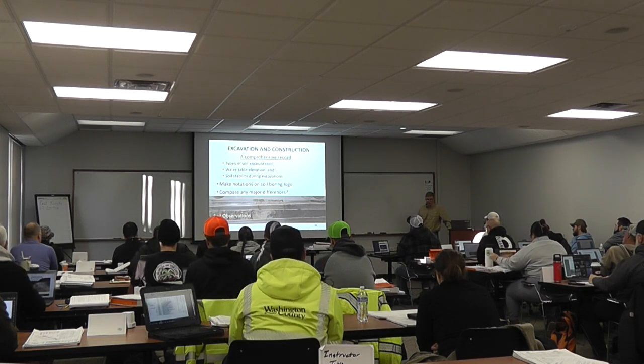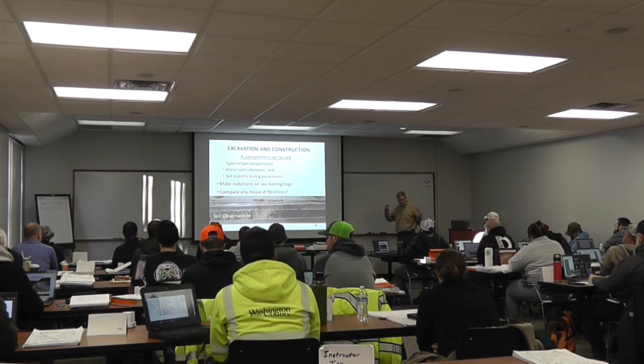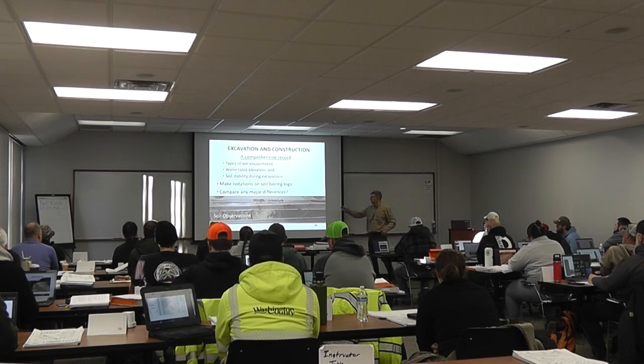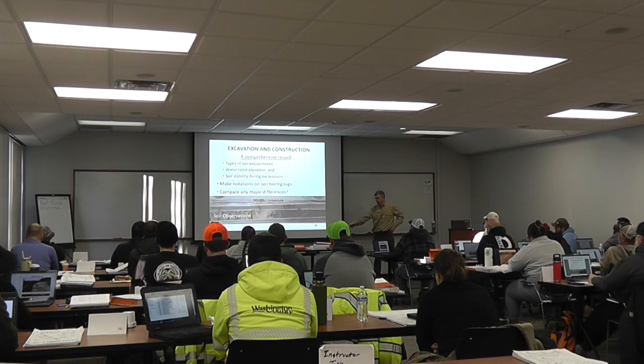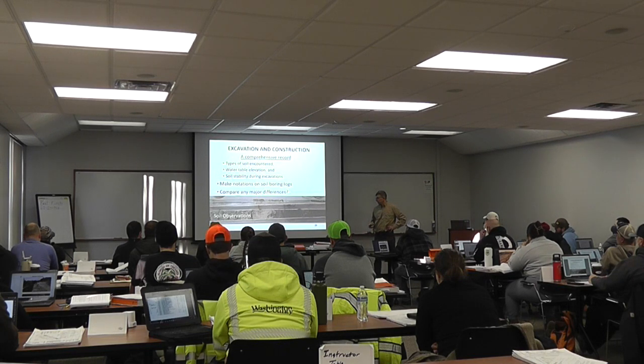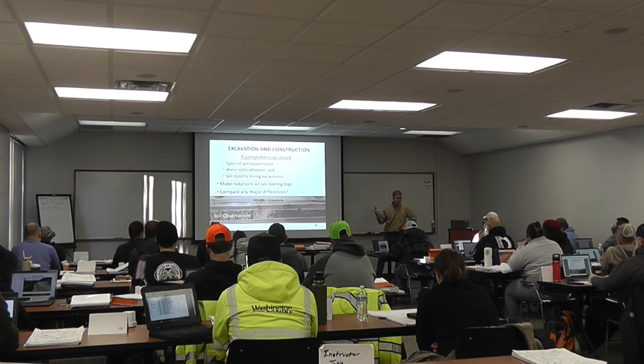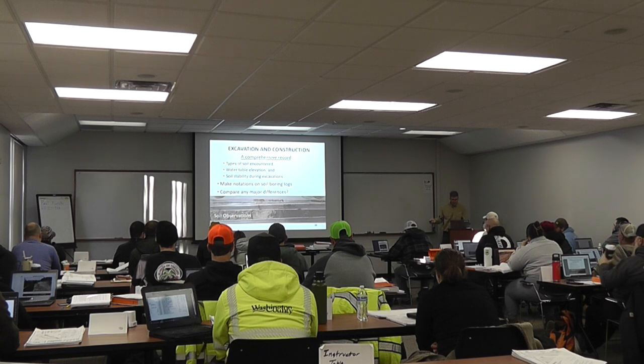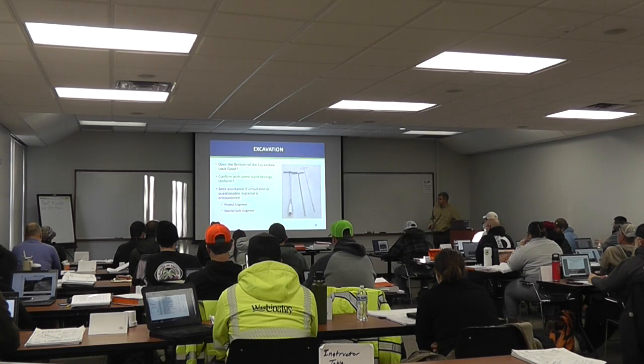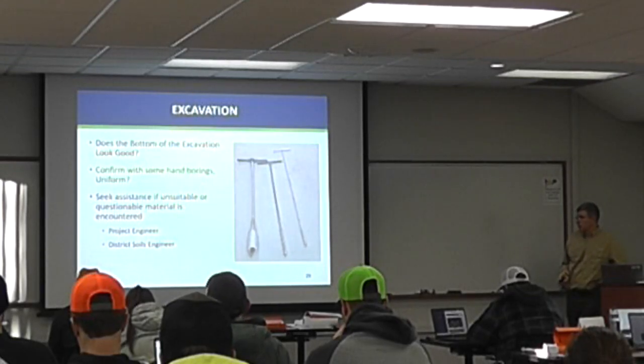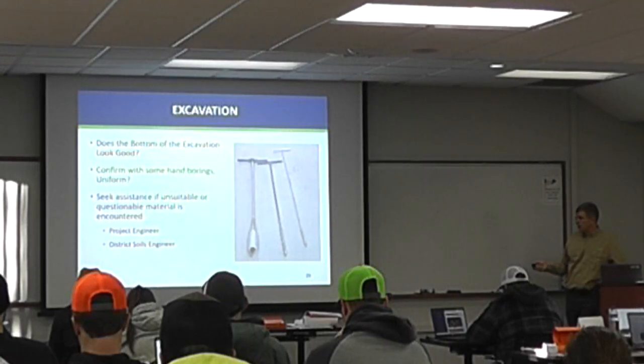So also keep track, not just perceiving, but make some notes on the boring logs in the back of our plans. Yes, this is what we saw, whatever. And then compare major differences. And if there are major differences, that's a perfect time to be asking the soils engineer, the geotech engineer from the lab, the regional construction engineer, what kind of things we've got. Sometimes you take some little samples and confirm with these hand borings, is everything uniform?